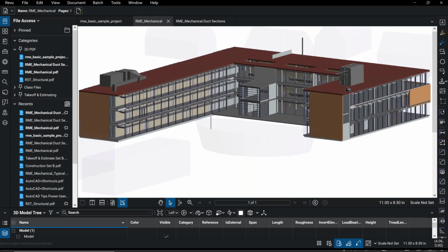So in this webinar, I will demonstrate converting an IFC and a U3D file from Revit into a usable 3D PDF in Bluebeam. We're going to look at creating this entire model from an IFC file, and we'll look at creating just one individual 3D view using the U3D file.